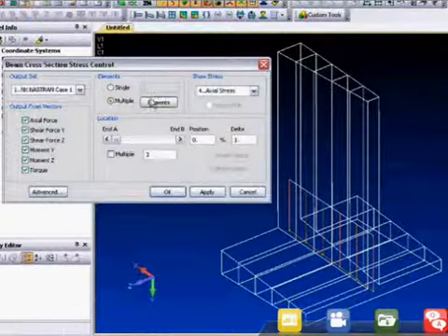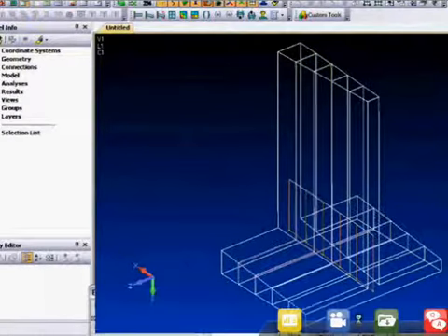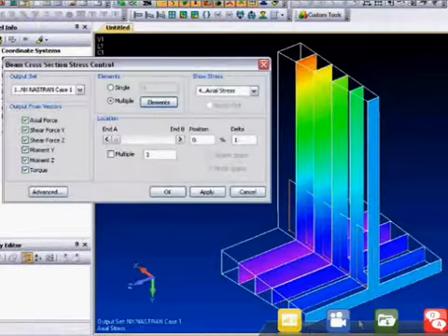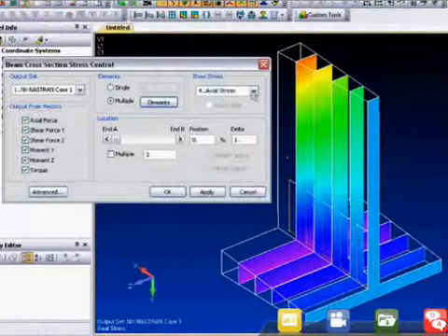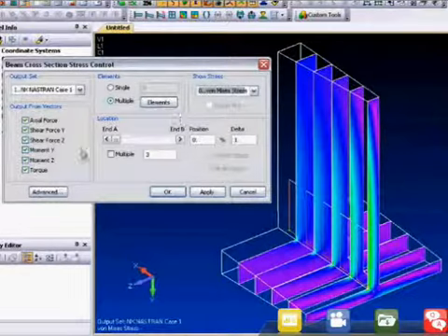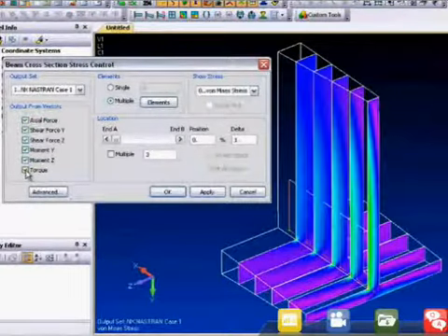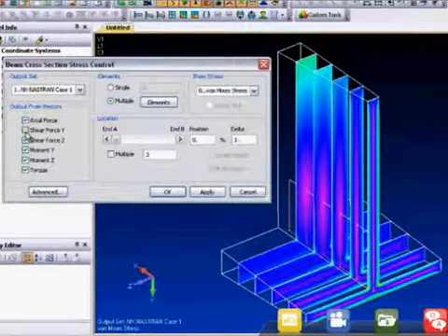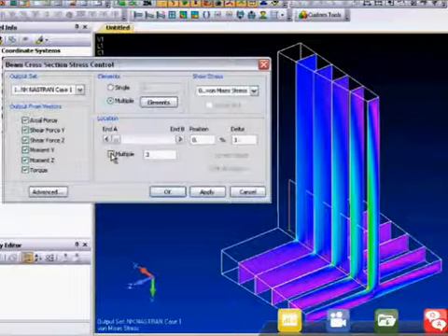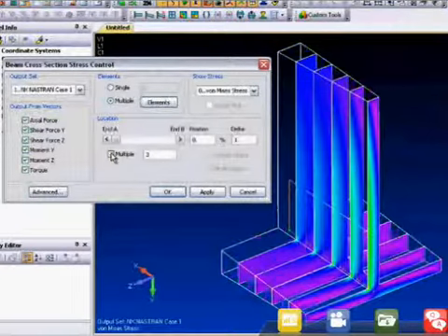In addition, you can calculate additional stress output that is not normally included with the output from the solver, such as von Mises stresses. You also have complete control over the force components that are used to calculate the stresses. So you can visualize stresses due to axial loading only, or bending only, or shear only. The forces themselves, axial, shear, and bending, can be recovered from any solver.